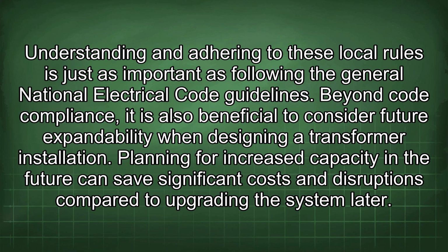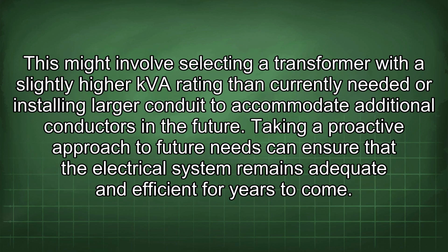Beyond code compliance, it is also beneficial to consider future expandability when designing a transformer installation. Planning for increased capacity in the future can save significant costs and disruptions compared to upgrading the system later. This might involve selecting a transformer with a slightly higher kVA rating than currently needed or installing larger conduit to accommodate additional conductors in the future.